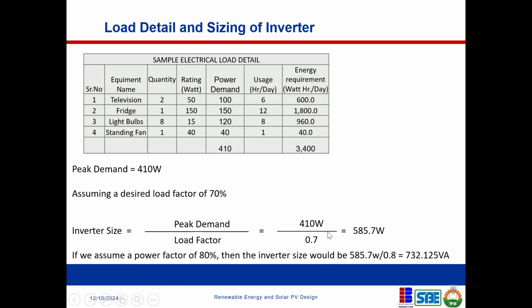Sometimes when you start some appliances, they draw more excess current at start, especially inductive loads like your water pumps. So you create tolerance for your inverter to withstand spikes and excess demand. I think 70% should be the ceiling.